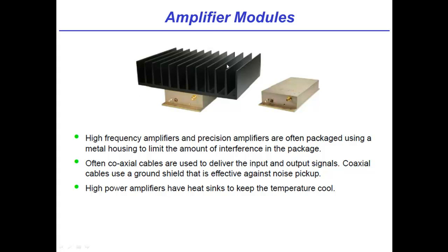And so if you were to open up a power amplifier or the inside of a computer, you'll find lots of these heat sinks. Heat sinks are basically large metallic fin type structures that provide a large surface area from which heat can escape to the environment. Makes sense. There's also a bunch of coaxes there. Is that right? That's right. These are coaxial inputs. Coaxial inputs are the types of inputs that you often see on the back of a television to which you would connect your cable, for example. That consists of a signal line surrounded by a grounded sheath wire. The point of that is it protects the signal line from external noise. And in many high-end amplifiers, particularly amplifiers running at high frequency, you will see coaxial cables used as the input.